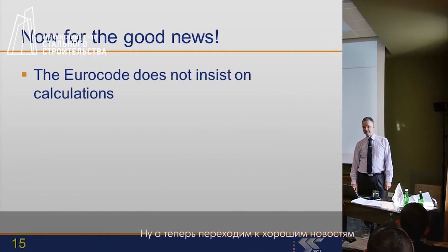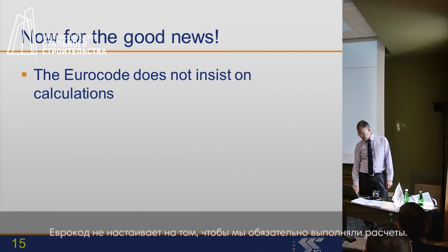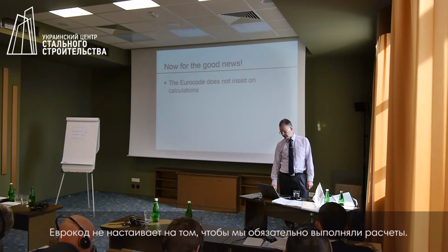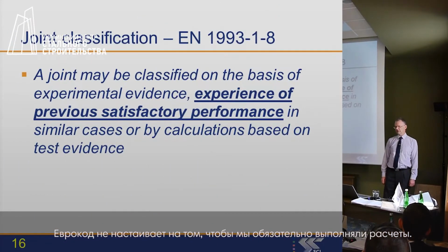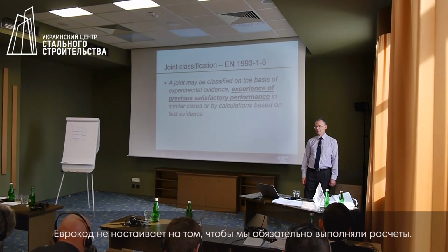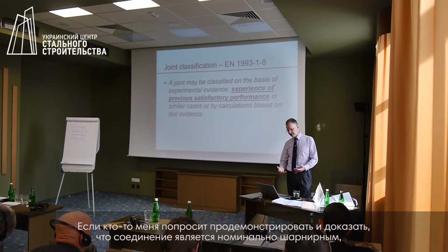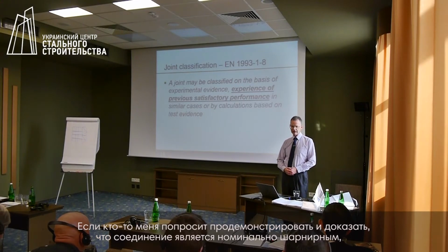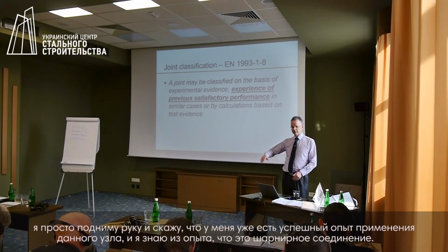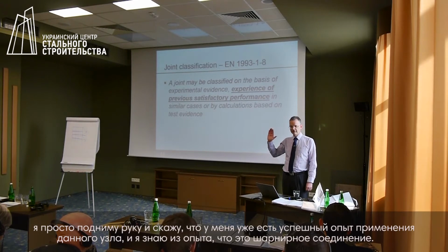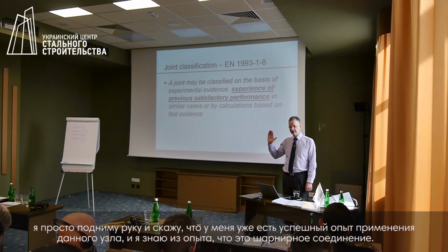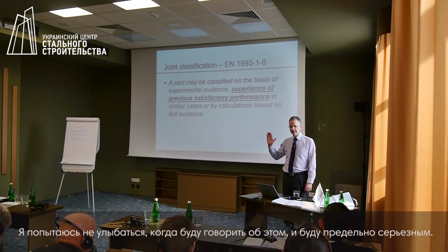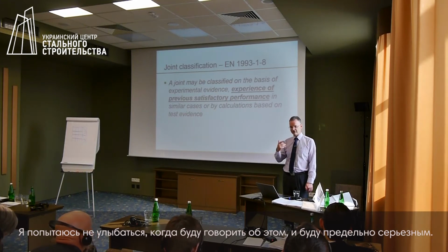So now for the good news then. The Eurocode does not insist that we perform calculations. The Eurocode does say that we can classify on experience of previous satisfactory performance. So if somebody said to me, David, please demonstrate that your connection is pinned, I would put my hand in the air and I would say, I have previous satisfactory experience of this connection and I know that it is pinned. And I would try not to laugh, I would try to say that seriously.